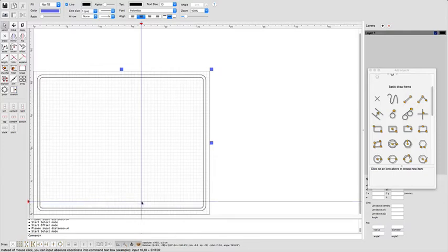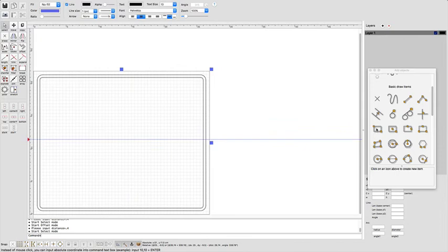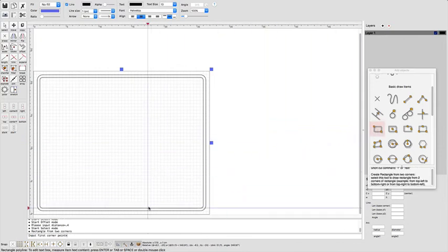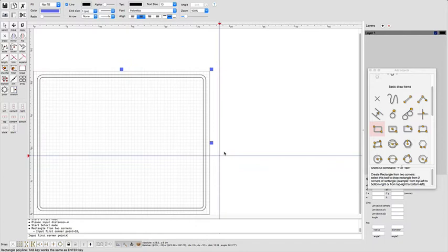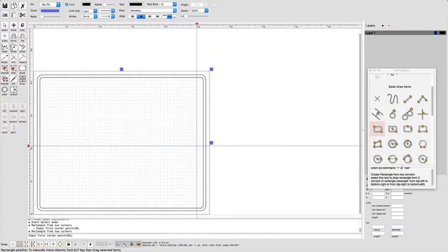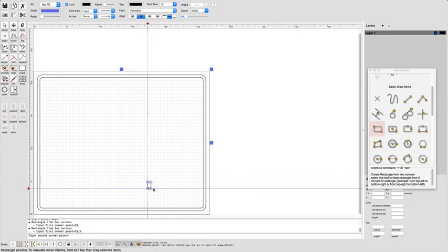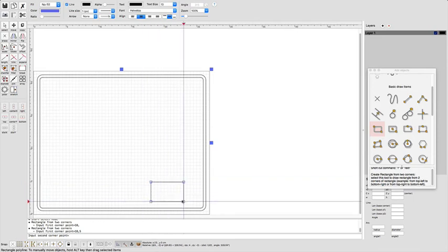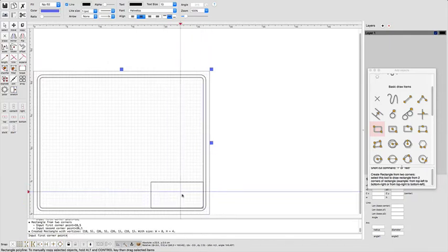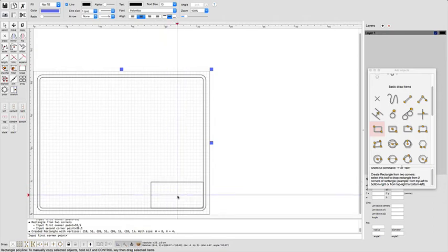So here what I'm going to do is have you draw another rectangle. And I'm going to have you draw that rectangle right here. So I'm going to go up to a point on my screen that is 18 over, I'm going to type this in actually just like we did before, 18 comma 5 as my coordinate. Enter, and there you'll see my anchored spot. And I'm going to do that all the way over to 26 comma 1. And there we go. So that now gives me an area to put in information.